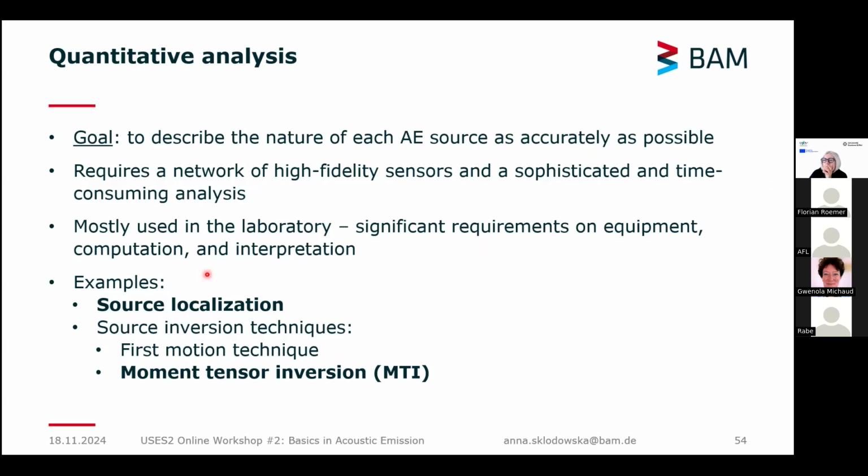But coming to the second part, we also have the quantitative analysis, and the goal is to describe the nature of the acoustic emission source as accurately as possible, rather than concluding about their effects measured at the sensor location away from the source. This is quite a sophisticated approach and requires a high fidelity network of sensors and a sophisticated, time-consuming analysis. So it's mostly used in the laboratory because there are quite high requirements on the equipment, computation, and also interpretation. So we need relatively simple objects to give a proper interpretation.